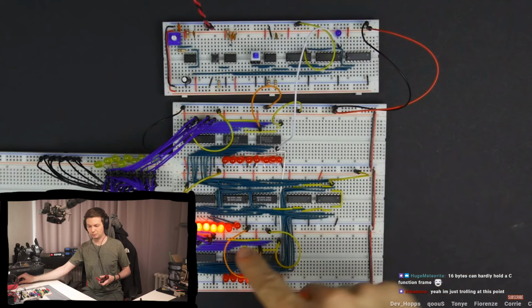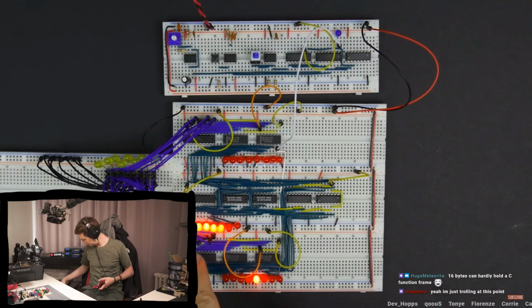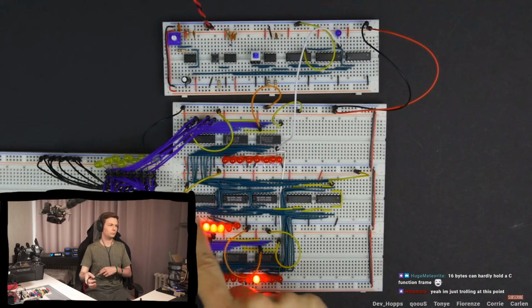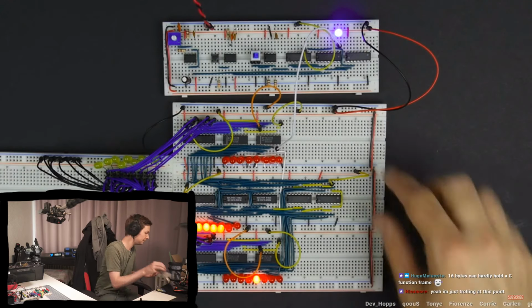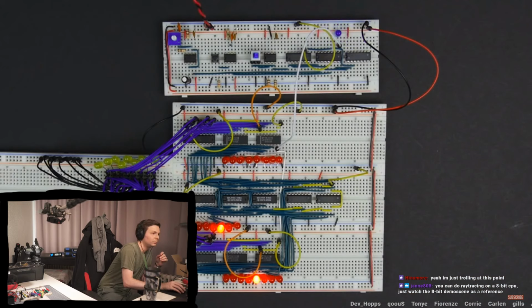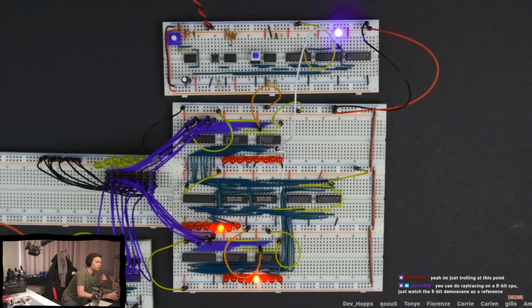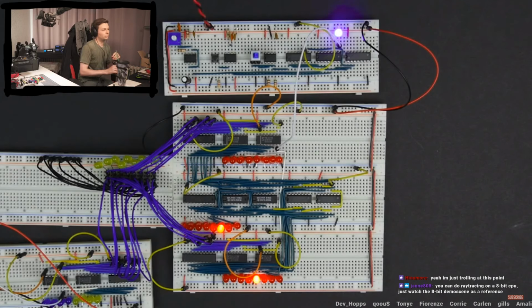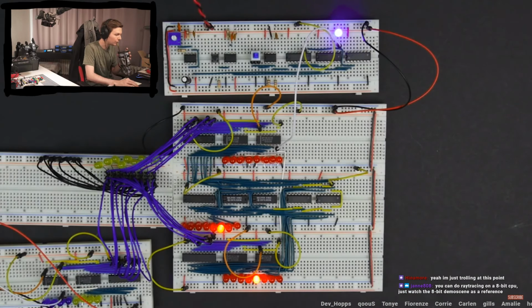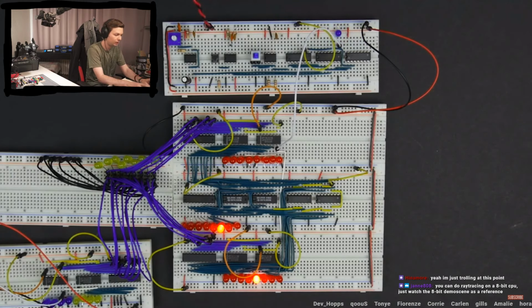And then when I switched from adding to subtracting, I'd expect to see a negative 8, which is, I think, 5 zeros followed by 3 ones. And I'm seeing something different. So something's not working right about this, which frankly happens probably the majority of the time when you build something new. And I thought rather than trying to find it myself and just swapping a cable or something, whatever it is that fixes this, and then editing that in at the end, I'd actually go through with you my thought process and how I troubleshoot this.